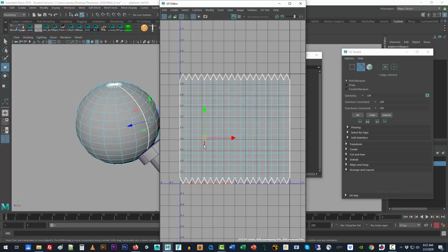So the first thing we'd have to do, just for an exercise of reading in a simple sphere, is you can double click along an entire edge, and let's just choose several of these edges, because this is more of an experiment of how the tool set works. Now we can cut these edges. The problem is, we're going to cut these edges, and then we're going to relax the entire UV set.